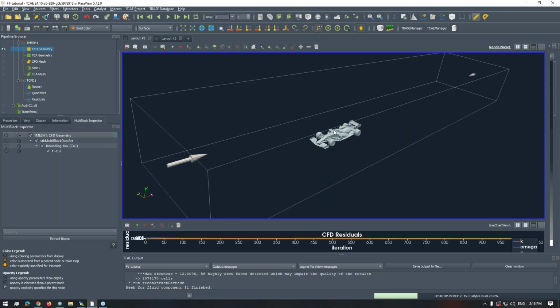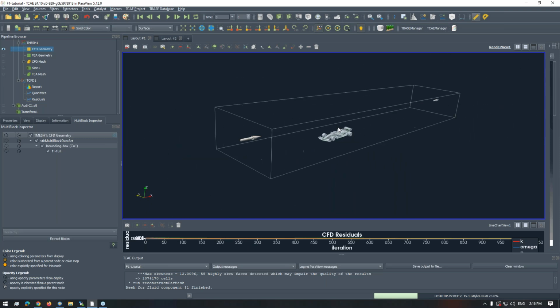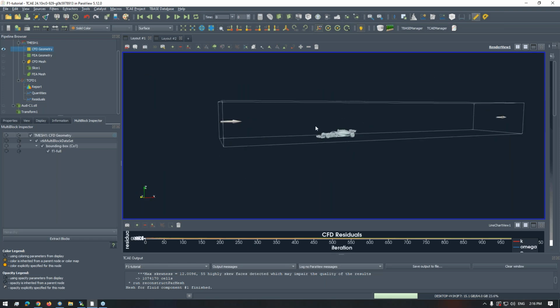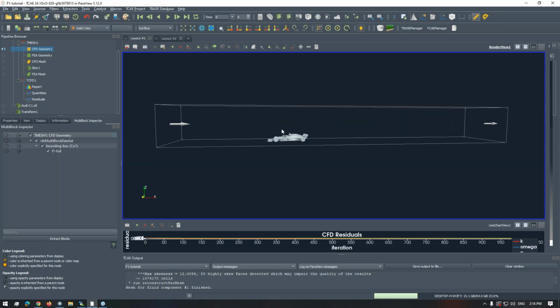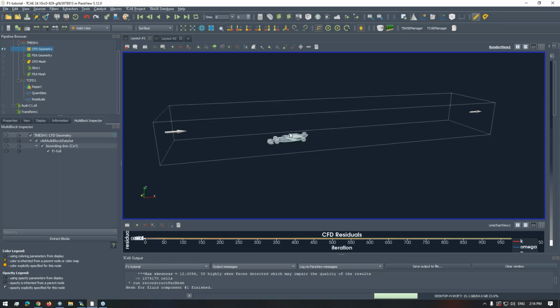Okay, and when we talk about external aerodynamics, we almost always put this object into what? Into this virtual tunnel, which is a box basically, where we say, okay, the object is typically moving, but to simulate the movement in this Eulerian space, to make it a little bit simpler, we will keep the object steady, and we will flow the air around it.